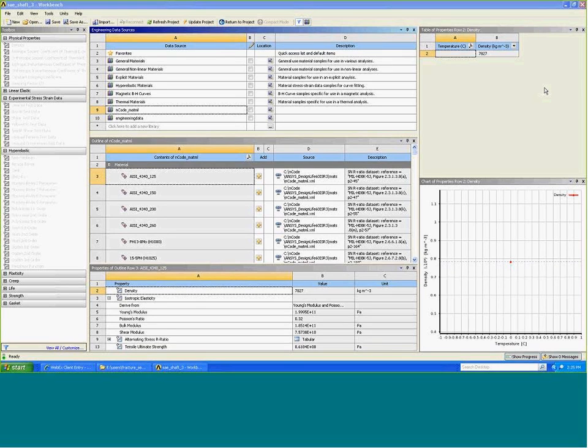In Workbench you tell it what type of fatigue analysis we're going to do, and it will automatically set up a default flow for you, which is really nice. And then I think the third advantage is that all of the analysis data that you get from both the finite element analysis and the fatigue analysis will get stored as part of the Workbench project. So you'll get the fatigue analysis right inside Workbench, as you'll see.